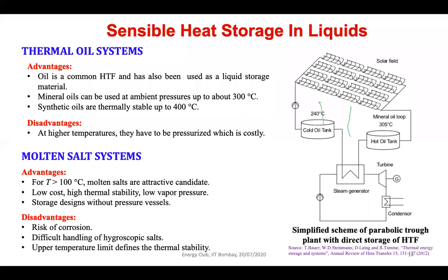Nowadays, molten salt is coming into the picture. So molten salt can act as a heat transfer fluid. It can also act as the thermal storage system, which I will show you later when I go to the latent heat thermal energy storage, because it has some latent heat content also.